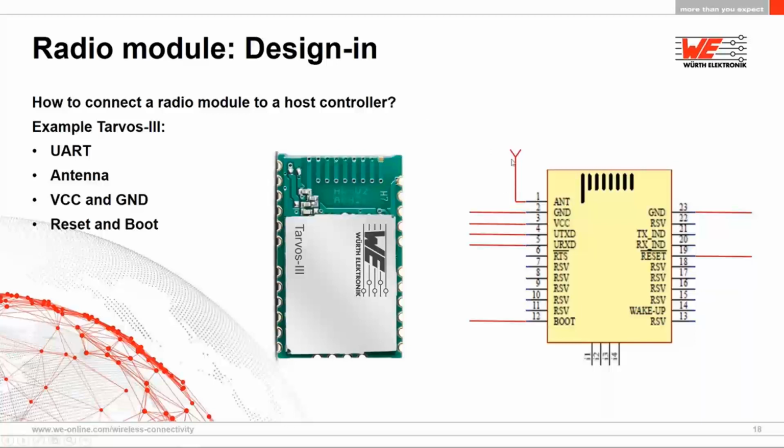One last little point, the antenna path here on your PCB, try to give it a 50 ohm impedance. So do a bit of calculation. There's some examples on the internet as well, where you can do a bit of calculating on the path width and thickness in order to get a 50 ohm impedance, especially if your path to the antenna is fairly long.